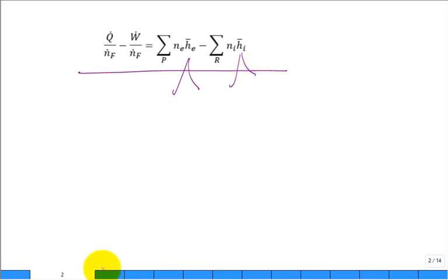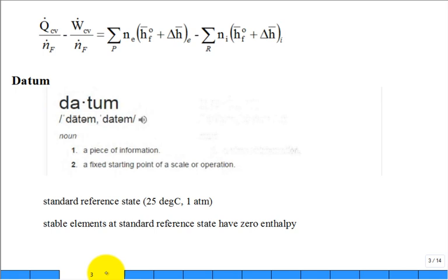Go back to our tables, or even chapter 3. There's a very good discussion about datum points. In our steam tables, our energy measurements started with the triple point of water, and I believe it was the saturated liquid, so u_f at the triple point, I may be wrong, I have to look at it, is set to be 0. And measurements go from there.